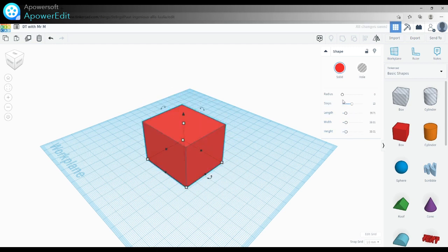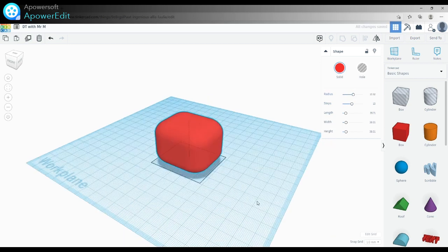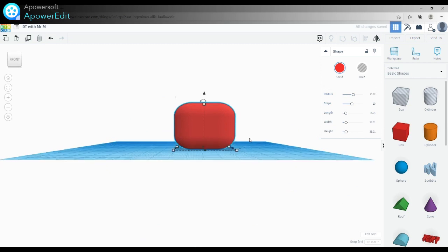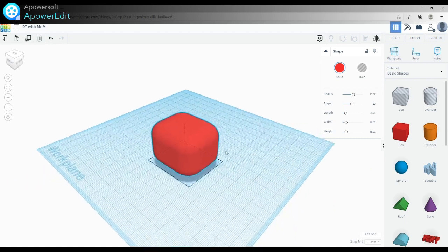We can also round the corners, and there are a few issues with this, and I'll come on to this in another lesson. But when we put a radius on, it's essentially putting it onto the cube. So when you do it, if you stretch the object, you also stretch the radius, so just be aware of that when you are using this as a program. Okay, when you're using this to create things.